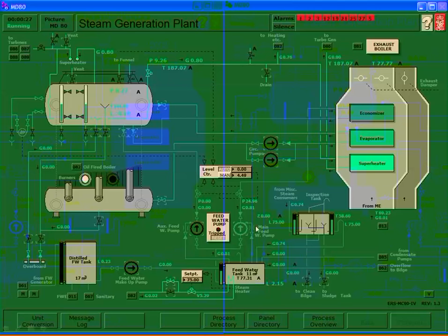On ours, one of the things here is, you notice you have the main feed pump and you have the auxiliary feed pump. The main feed pump feeds into the economizer and then into the drum. The auxiliary goes straight to the drum. So this one is designed for combined cycle out at sea. This one, by the way, is really used in port.